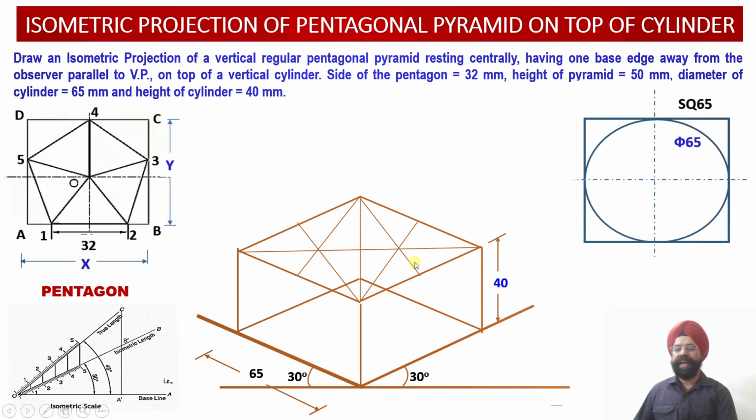Now once we have made these constructions, next all the four centers will be located, which will facilitate the construction of the geometric figure of the ellipse over there. And the name of this method is called the four center method. So this is my center number 1, this is my center number 2, this is my center number 3, this is my center number 4.